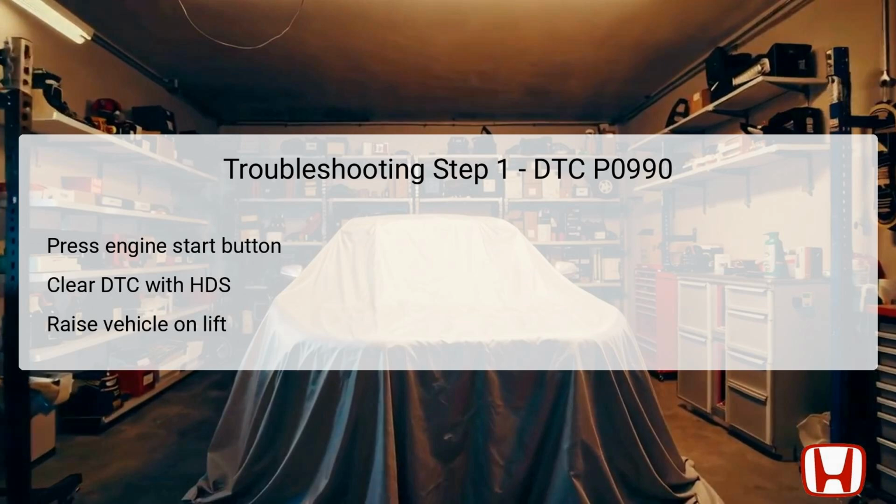Following this, it's vital to clear the DTC using the Honda Diagnostic System, HDS, allowing the system to reset and potentially reveal any intermittent issues. Next, raise the vehicle securely on a lift or apply the parking brake if on the ground. This step ensures that you can safely inspect and allow the front wheels to rotate freely, an important factor for checking fluid dynamics and pressure readings. Each of these initial steps lays the groundwork for effective diagnostics, ensuring that the subsequent actions can be performed safely